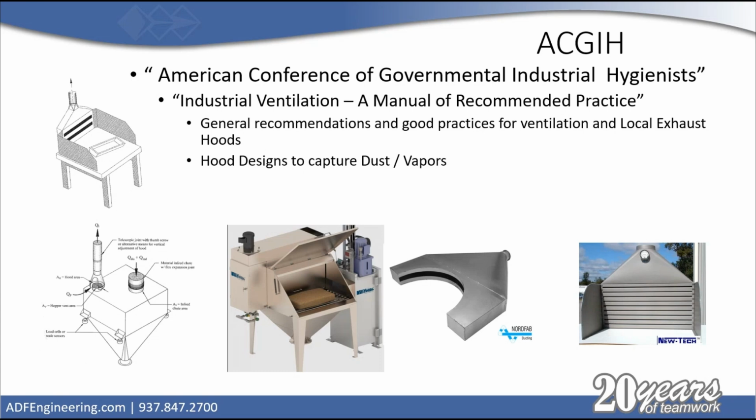So on this picture, just to take a bit of a look, in the upper left is kind of a slot hood table that can be used if you are dumping bags, they can be modified for bag dumping. Although in a bag dump, we would want to go to that midsection, which we would prefer a downdraft hood, because that keeps any dust out of your breathing space. Whereas a slot hood will also, but if you were to put your aspiration above those, then you would pull any dust that was generated past your breathing zone before being aspirated, which you don't want to do.